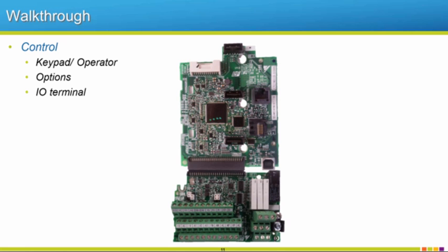Then we have our terminal board full of our inputs and our outputs: all of our digital, so our ones and zeros, and our analog signals, our 0 to 10 or 4 to 20 signals, are all located on our terminal board down here. This terminal board is nice. It has non-volatile RAM, so if something was ever to happen to the rest of your drive but your terminal board was okay, you could just use your old terminal board in your new drive, as long as certain things are kept the same, like the same size, control method, and software revision.